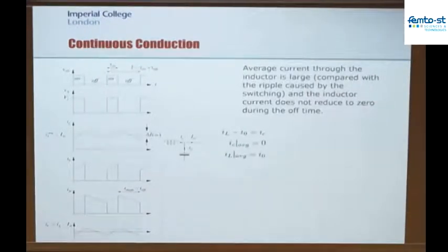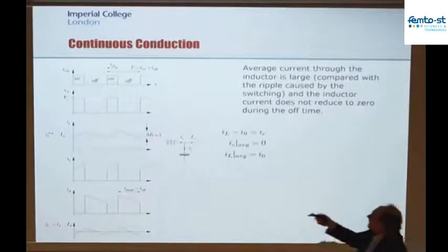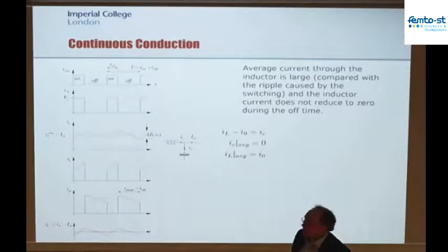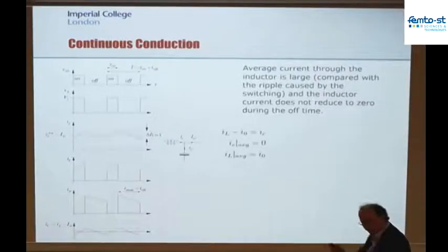So in terms of the actual graphs showing us here how the circuit operates, we apply a pulsed gate voltage here onto the MOSFET, going between on and off all the time. You can see here that we're operating with about a 30% duty cycle, which is what we were wanting to go from 15 volts to 5 volts.